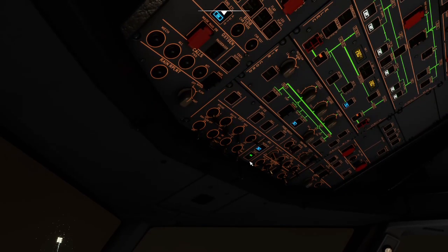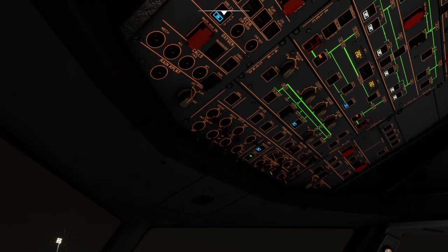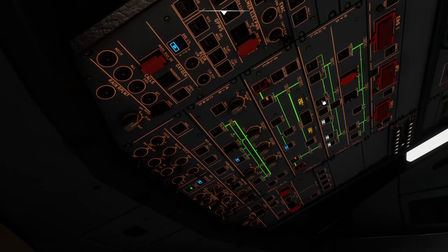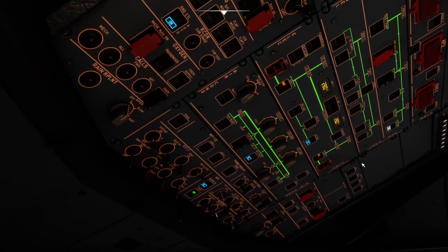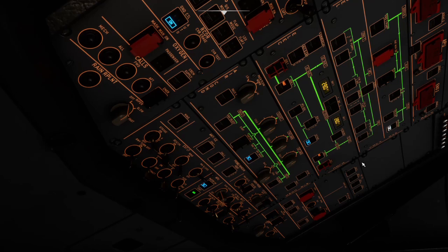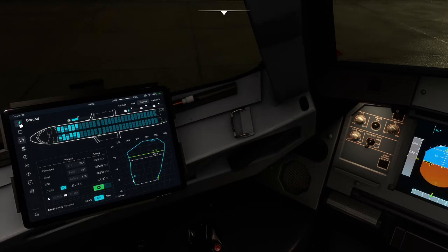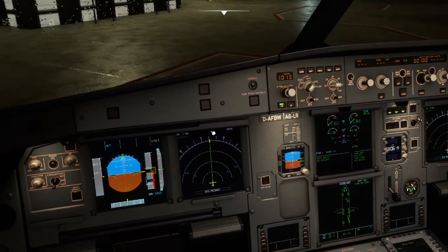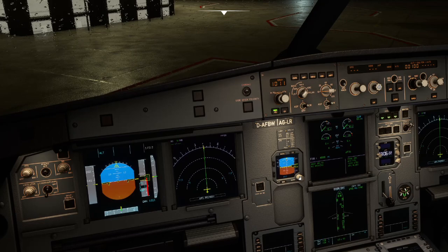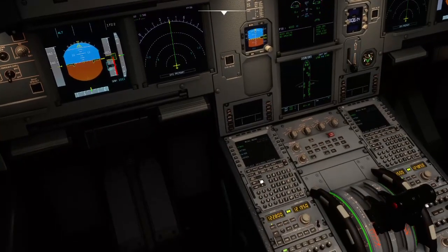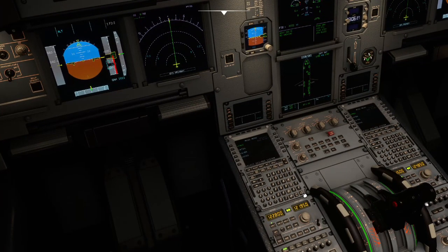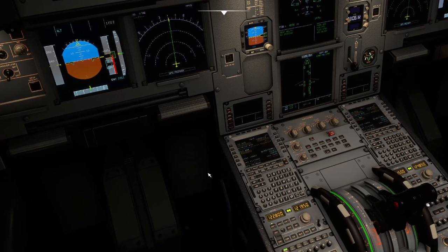I'm not an A320 pilot, I won't claim to be, so these are not in any particular order. We do have boost pumps going, the electric standby hydraulic pump is tripped to on, and the seatbelt sign's already on. With the hot power up, that's all we need to worry about for now. Having a quick look, reset on both, down to the FMGC, trying to get initialization going.